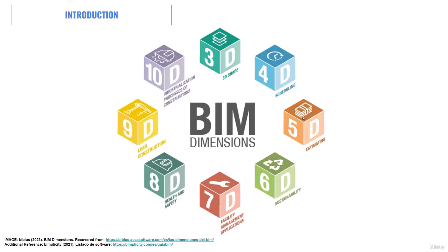So you can pretty much use the BIM model to generate automatic quantifications and integrate everything to the unit prices of each type of element. So pretty much you can start working on your budget, and in a semi-automatic manner you can optimize your workflow for this dimension. We got additional dimensions such as 6D, which is related to sustainability, which incorporates the solar studies of the project, the wind design elements, all types of energetic evaluation, and even more specialized processes related to the